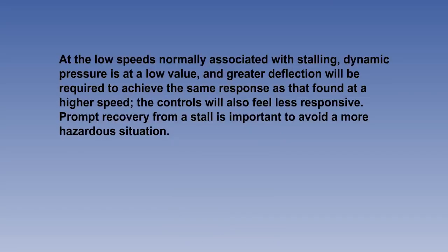At the low speeds normally associated with stalling, dynamic pressure is at a low value, and greater deflection will be required to achieve the same response as that found at a higher speed. The controls will also feel less responsive, as mentioned earlier in the lesson. If an accidental stall should occur, it is important that the recovery is effected before the process develops too far, with a large wing drop giving a high rate of descent or possibly leading to a spin.